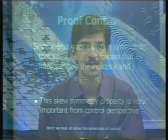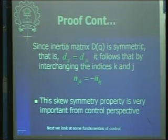Suppose now in place of k and j, you just put j and k and see what expression you get. You will find that if you replace k and j, you get N_jk is equal to minus N_kj. Do you see that? So we have generalized this property for the n-link robot manipulator.